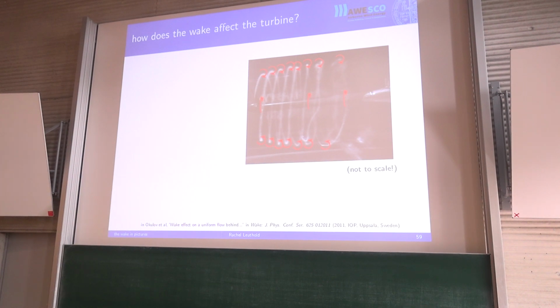Okay, so one thing you may notice is that on a given side of the turbine wake, the circulating motion patterns are always oriented in the same direction. Which means that at some point you would expect that there would be some component of velocity that's pushing back upstream here, right? And again, some component that's pushing downstream here, right? Just from looking at the sum of these circles, or circular motions, right?